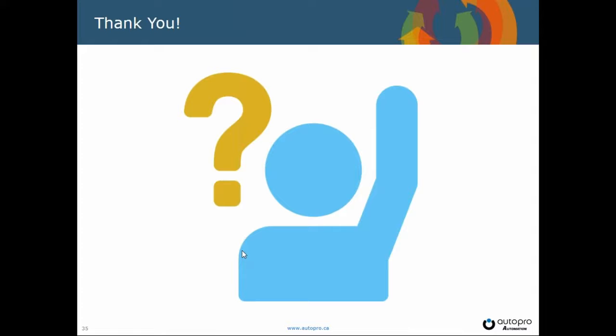A CHAZOP may not have to be done quite that often, but the difference is that a HAZOP assumes the control system is operational and working, whereas a CHAZOP looks beyond that and into the control system. It looks at your network, your remote IO network or your peer-to-peer networks, and what happens if they fail. Do you have to do it regularly? No. But it would be a good idea to do it as part of an upgrade or an expansion to an existing system.